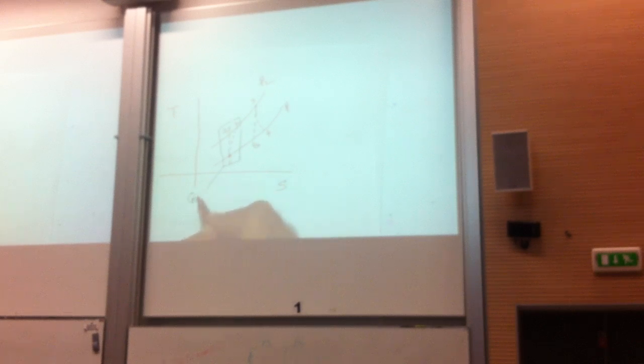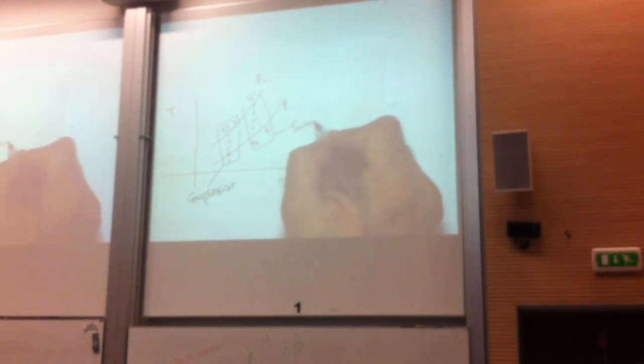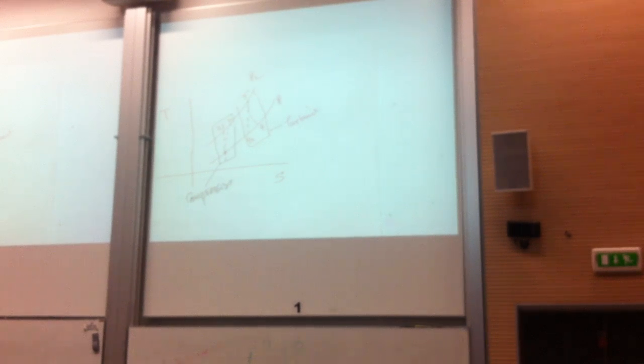So the lower configuration, this one, is a pump or compressor. And the upper configuration, this one, is for a turbine or expander. If you are good at steam tables and you know this diagram, no question in the turbo machinery section can trouble you. This pressure will be given, this temperature may be given. You can go up, you have got the entropy. Once you are there, you can determine the temperature at 2S.